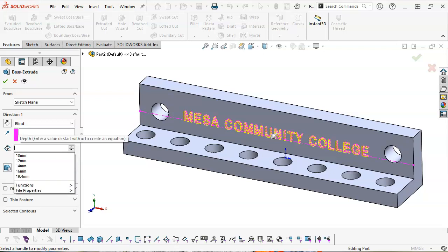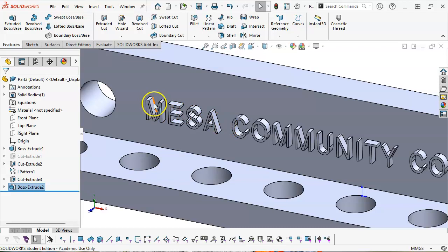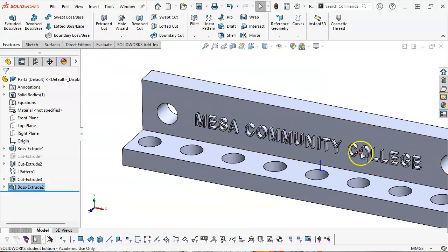So maybe not that much. Let's go 2 millimeters so you can see it. The downside to this is all of these sharps, the end mill would have to go through and pick those out. A lot of geometry, a lot of time, and that's small. Even with the radius, that small of gaps in geometry, well, that would be an issue.